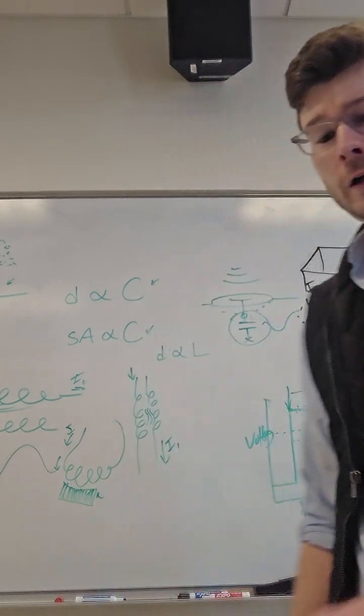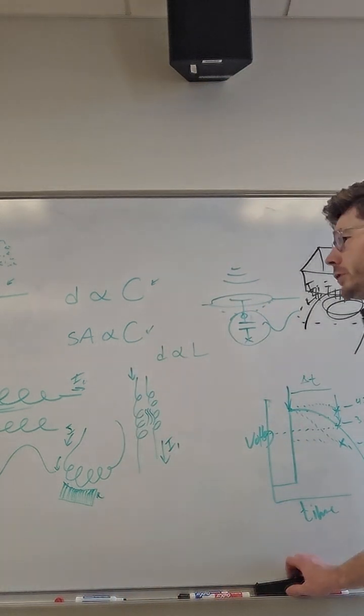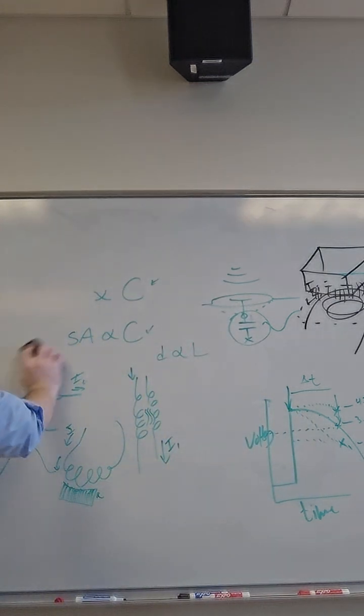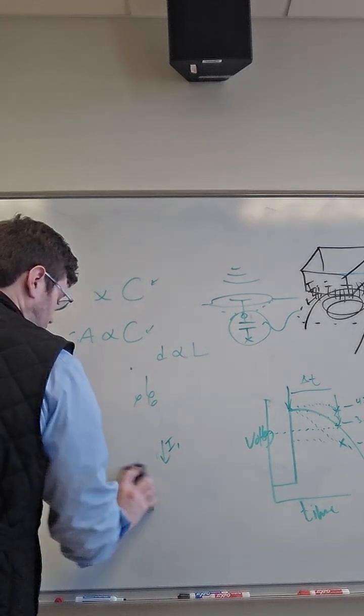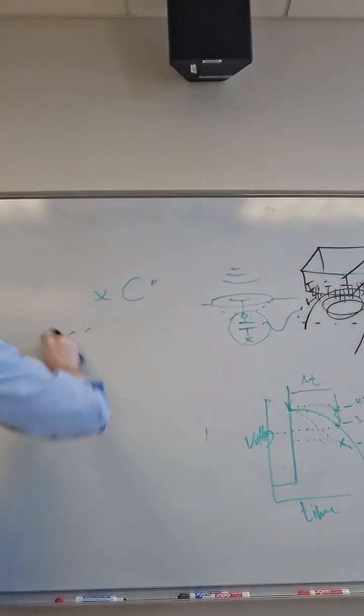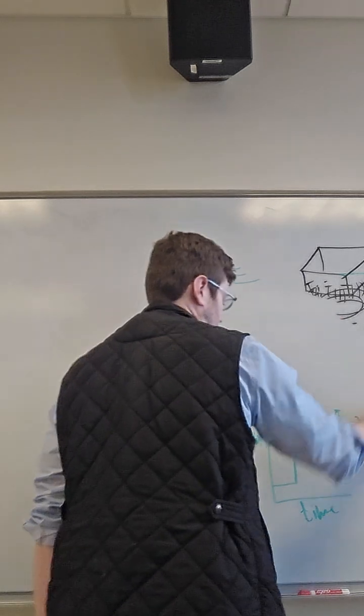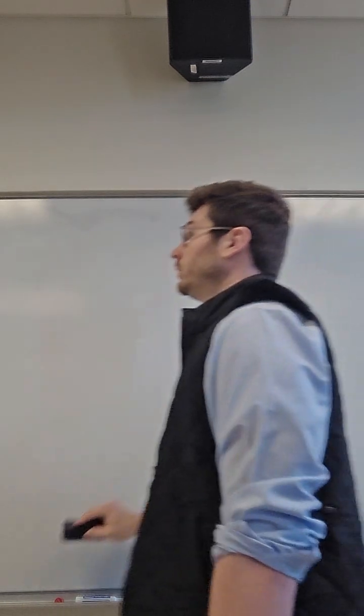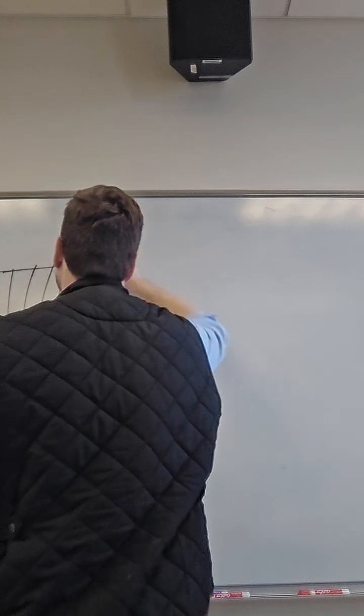All right, and then the other example that I gave for the capacitor is how your touch screens work. Again, they used to use resistive touch screens, which pretty much just registered where on the screen two pieces of film intersected, where one could tell where you touched on the Y direction and one could tell where you touched on the X direction. This one's similar, except it breaks up the phone into a group of cells, and then each one of those cells is charged just like we talked about before.